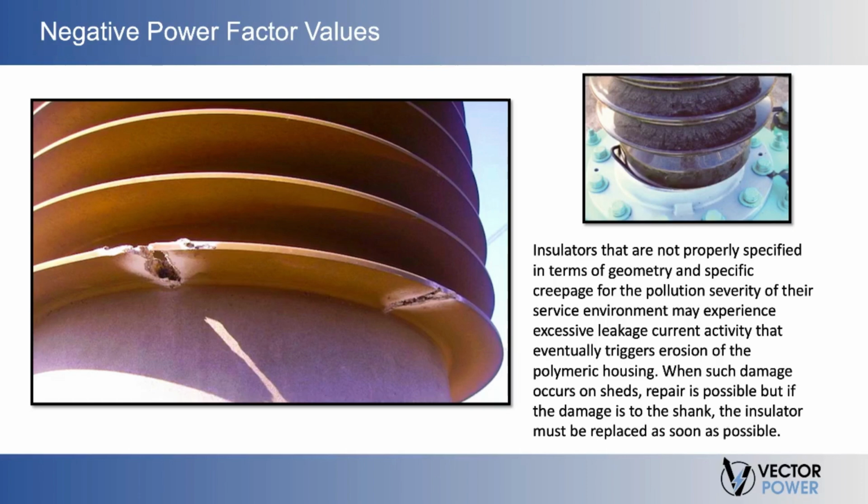This condition is most likely to arise when making UST and GST measurements on specimens that have a capacitive value of a few hundred picofarads or less. Equipment such as bushings, circuit breakers, and low-loss surge arresters fall into this category.